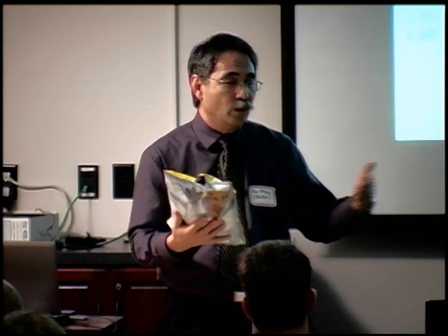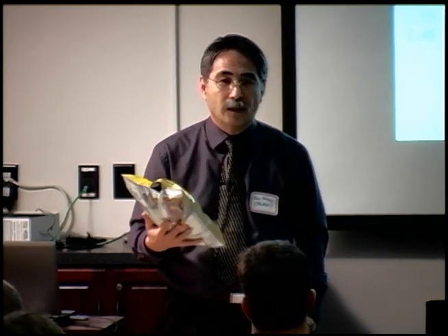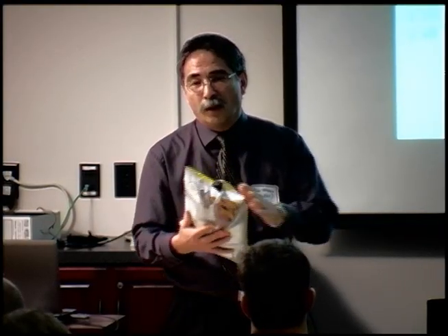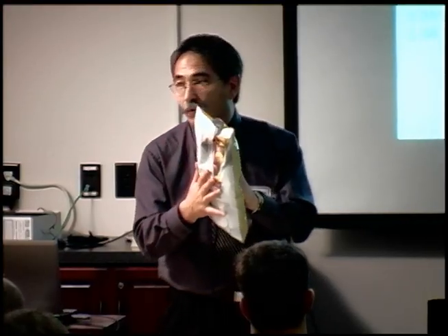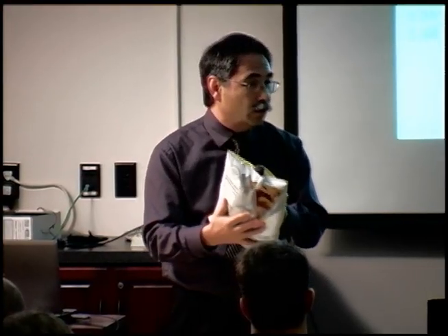It's no different than what we're doing with spread footings or a half dozen other things in soil mechanics. Does that make sense? And if we get into organic soils and secondary compression, that gets off target, but then it's crushing, right? The skeleton starts to crush.